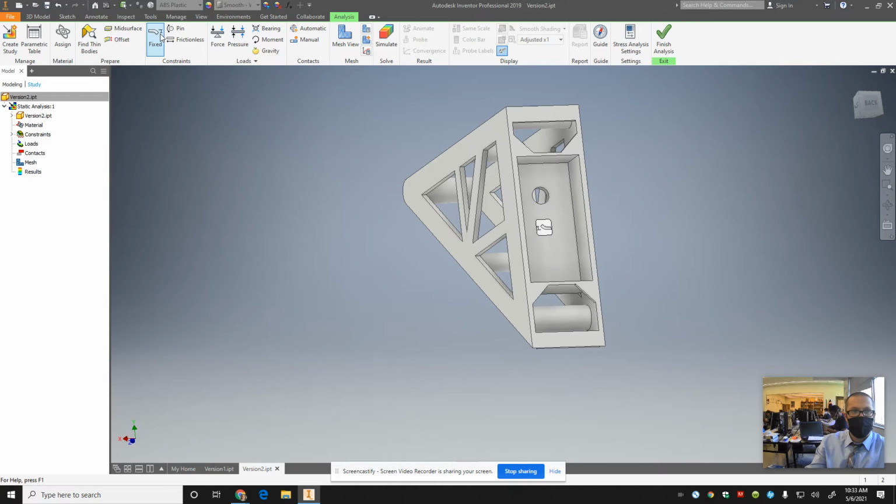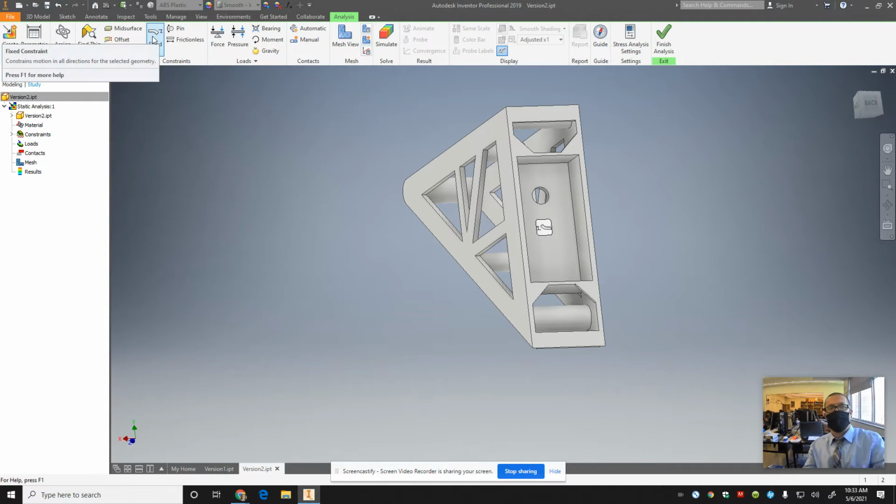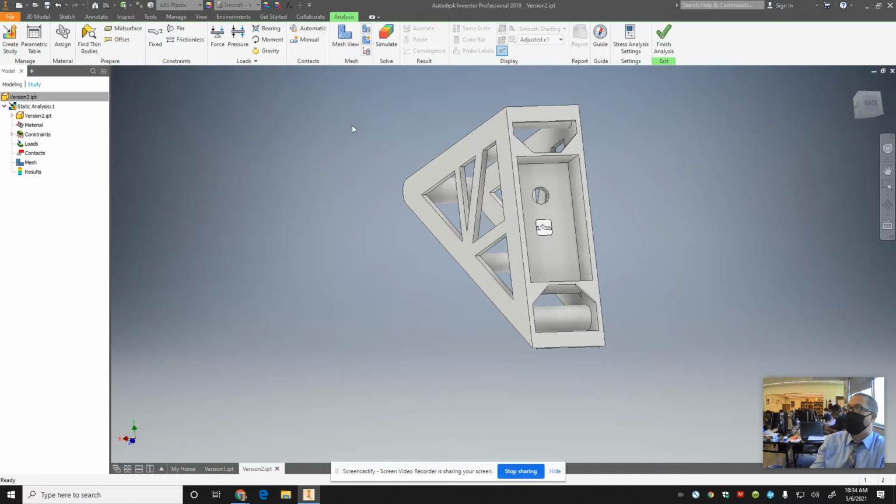And if you look at the preview for this, it shows you, like this one here in the preview, that bottom part must be bolted down or something. So that's going to be attached down. The top one's going to have the stress on it. So let's see where the point is. And it's going to make like red area where the stress is. So if I pin that interface of this, if I fix it, that makes sense because that's what's going to be bolted down to the block.